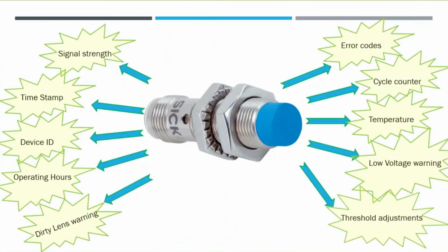This also has all these detailed information stored inside it. The only issue is how do you get it on the field bus protocols? How do you get it on that field bus levels? Because it obviously doesn't make sense to put on an Ethernet port and connect the sensors directly, right? I mean, the cost of the Ethernet cable itself might be more than the sensor.